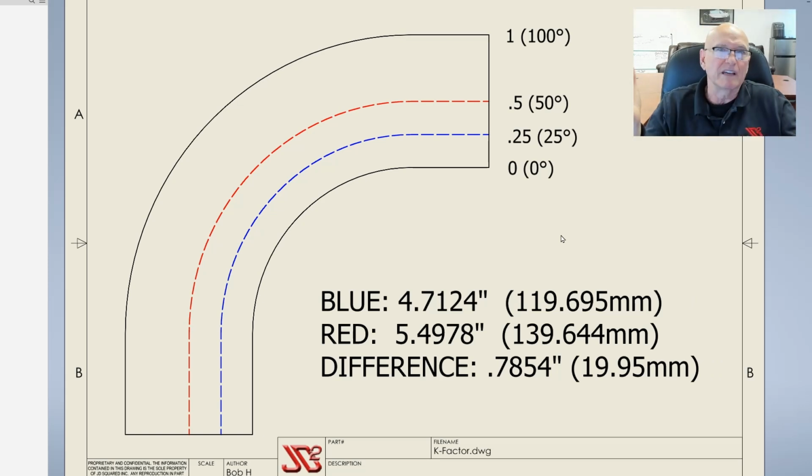I'm just making up numbers here. That's probably because of the heat treatment at the factory of the material. For instance, I believe I'm correct, on tubing, mild steel we're talking about, welded seam, the tolerance is plus or minus 11%. So you could go 11% hard, you can go 11% soft. The softer the material, the more it wants to stretch, and that changes the K-factor.